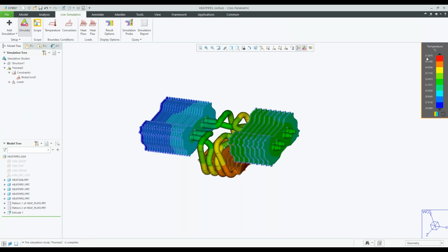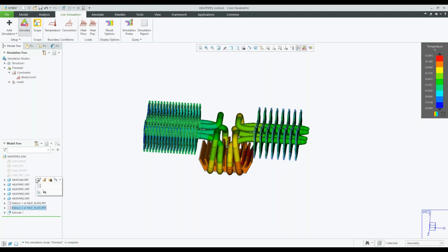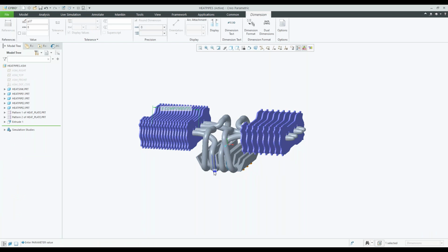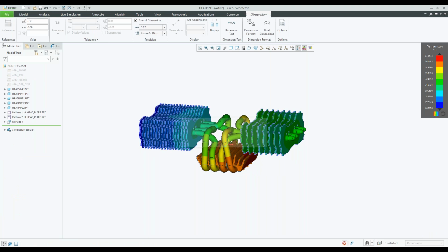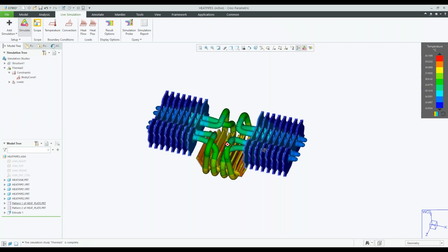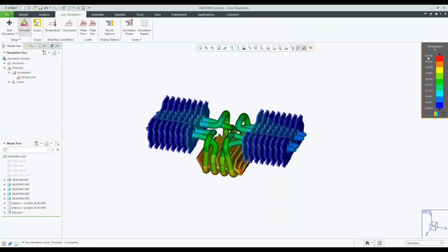Okay, so you can see we're picking up a little bit of heat. Remember, we're trying to stay below 40. So let's change the other side as well. We're going to go to 8 components, and make the spacing 6. I'm going to regenerate that. Okay, so now we broke that 40 degrees Celsius that we don't want. So maybe I went a little bit overboard with those fins.